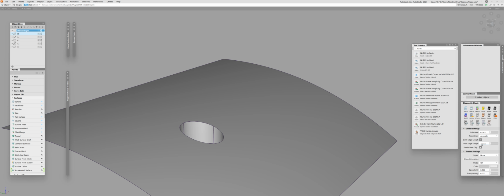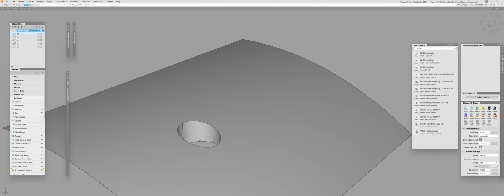Right now the edge length is 1. I believe it is 1 millimeter, and it means that now, independently of the curvature, it will still create the loops all around the model with a step of 1 millimeter. And immediately, as you can see, the issue is gone.